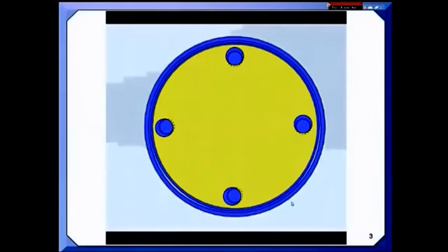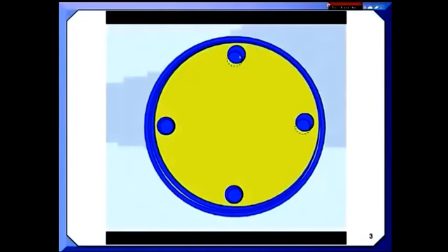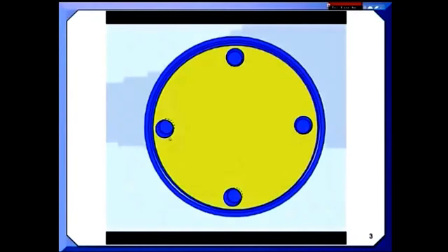Here's an animation that shows the result if you treat that M as though it were giving you a bonus. Yeah, I can shift the part around at assembly, but if you gave a bonus to the position tolerance because of the M on datum feature B, I might only get these two screws to go. Then I could take those two screws out and shift the part down to get two screws to go here, but that would just be silly. So that's not what it means when you see that M on the datum feature. You can't give these clearance holes additional position tolerance.